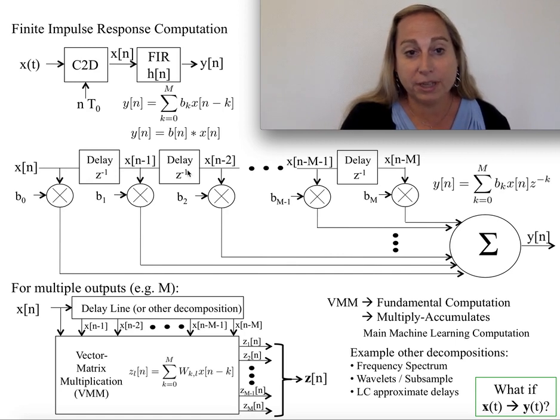Well, I'm going to do this as a delay. The interesting thing digitally is this is simply a register, a memory, maybe just a simple shift register to take the register bits here and then just move them over here. If you've done any digital implementation, you know it's one of the most straightforward and most natural things to do with digital circuits, with all the latching behavior and so forth. And so as a result, you can look at this whole structure and go, I create all the delay lines.